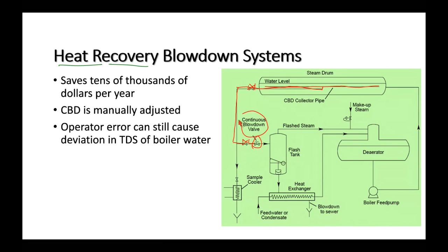Now, because the CBD is running almost continuously, it's a good place for us to take a sample as well. So we're going to have a sample cooler on there as well. But anyway, after the CBD water hits the flash tank, that flash steam and the heat that it carries, so the materials and the heat, get carried to the deaerator.